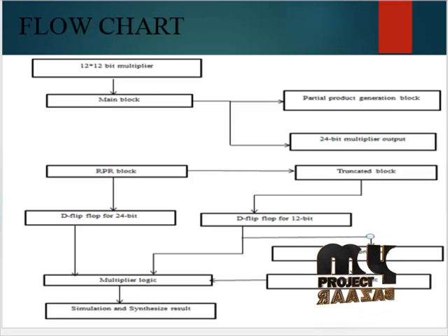Now we discuss partial product generation. The Booth multiplier has been widely used for high performance signed multiplication by encoding and thereby reducing the number of partial products. A multiplier using the Radix-4 algorithm is very efficient due to easy partial product generation, whereas the Radix-8 Booth multiplier is slow due to the complexity of generating the odd multiples of the multiplicand. In this process, with the application of approximate designs, a 2-bit adder is designed for the calculation of the sum of 1 and 2 binary numbers.